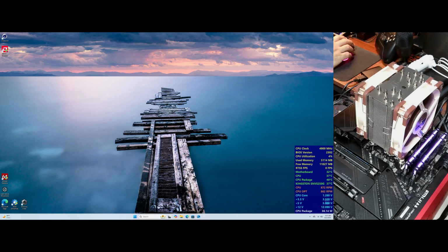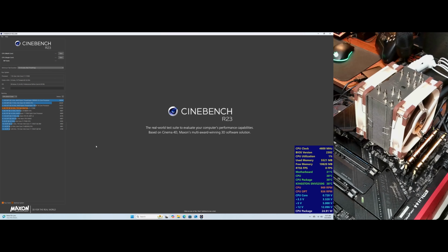All right, now we're back. Looking at the CPU core. Look at that. It's now jumping up and down with its lowest less than 1 volt here now. But we'll see, right? Now we try testing it using the Cinebench again. This time with an undervolt offset of 0.075. Okay. 10 minutes starts now.